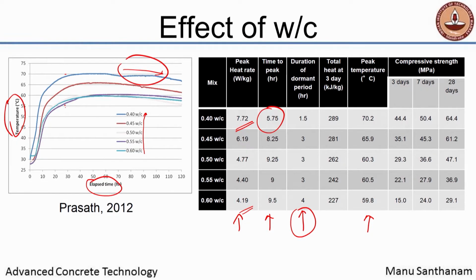Let us consider a system, cement paste system, which has cement particles in water. So, let me say those circles are cement particles, and the white space surrounding the cement particles is water. Okay. Now, this is a high water cement ratio system. Now, I have another view of a system that is a low water cement ratio system. So, what does it mean? That means I have more cement particles in the given volume.